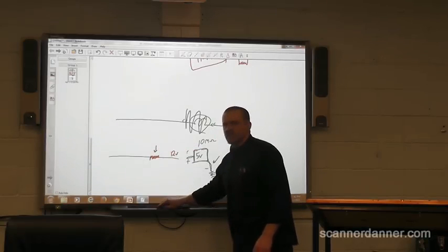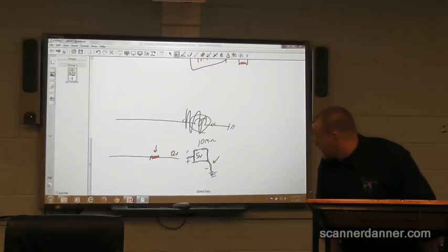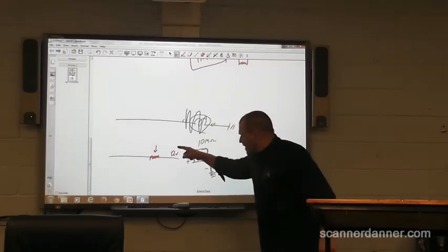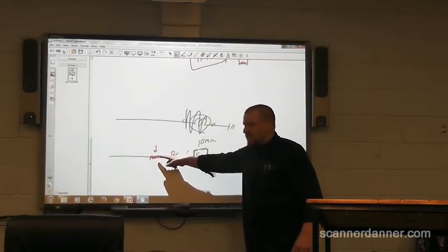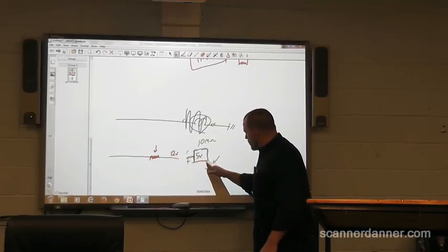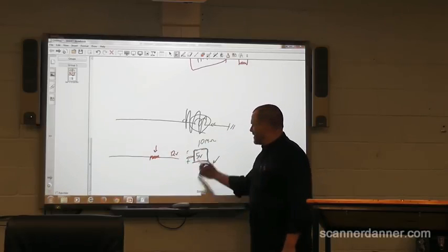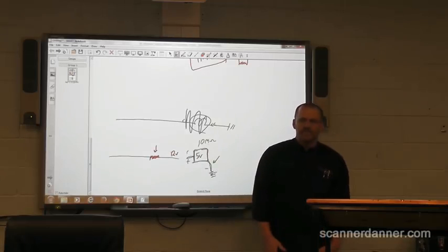I don't care what that resistance number is. But because you connected your meter up to that, and that resistance over there is so high, in the probably millions of ohms, as soon as you connect that meter up, it causes a current draw through your meter. Yeah, how much? It's 10 mega ohms of impedance. Not much, but enough to cause a voltage drop.